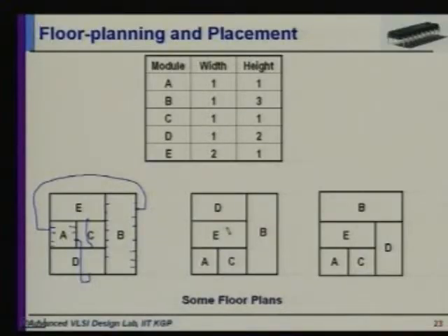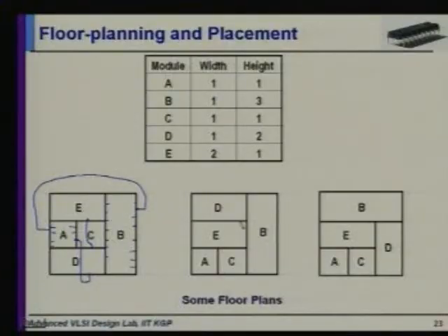Today people even try to think of interconnections well before you have actually started designing these blocks. You first start thinking, what are my blocks, where am I going to place them, how am I going to route them. Then you start saying, okay, this block has to be designed with this geometry. So you ask the synthesis tool to design it in such a way that it fits into the budgeted box.